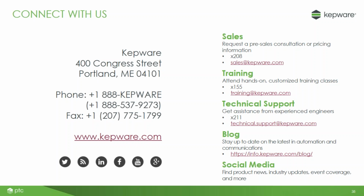Question from Carlos. Can we make any data calculation from multiple tags in KEPware? Or do we need to use a SCADA system to do this, like adding 2 tags? So great question, Carlos. This will give me an opportunity to plug our advanced tags plugin. If you get the advanced tags plugin, it is an extra fee. It does require an extra license. You can do those calculations. That's exactly what that advanced tag plugin is for. And again, we do have a webinar on advanced tags up on our website, and we also cover that in a module and go through an exercise in our regular training class for using that.